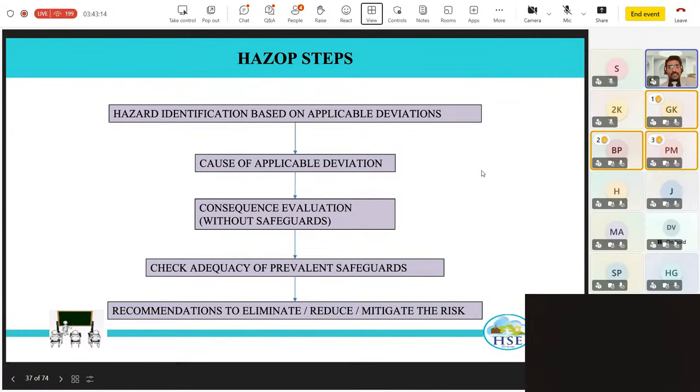Next are the consequences that the cause can lead to, the worst case consequence. Again, you could have 3 or 10 consequences. It is good to list all the consequences as per the worst they are impacting for that unit, or you have to list the most severe consequence. To give you an example, if you have a flare KOD, you have considered a tank, the vent routed to a flare KOD, and then that going to a flare.